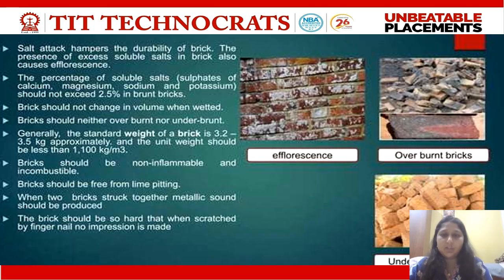There should be no white spots. As you can see in this diagram, white spots are developing on the brick surface. This effect is known as the efflorescence effect. Efflorescence is nothing but the reaction of free lime with water. I'll be discussing it later during the testing section. The brick should be non-inflammable, meaning it should not catch fire. It should be incombustible. It should not burst. They should be free from lime pitting. When two bricks are struck against each other, they should create a metallic sound.